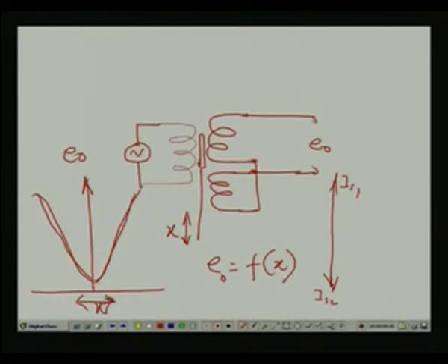Now, you see there is always some null voltage which will appear. This will be Ex, the excitation, right. For this movement you will always find there is an output voltage, and between this excitation voltage and the output there is a phase difference, which is an undesirable property.